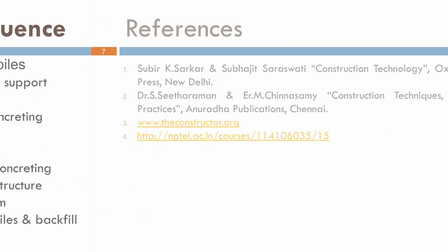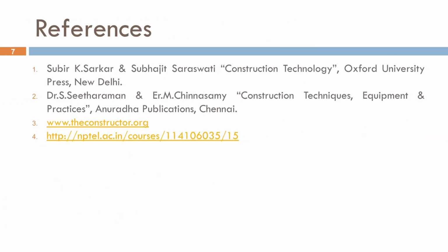To summarize, a cofferdam is a temporary but extremely important structure that allows engineers to construct foundations safely below the water level. Today we discussed its definition, planning considerations, different types used in water and on land, and the complete construction sequence. Whenever you see a bridge being constructed across a river, chances are that a cofferdam is playing a crucial role behind the scenes by providing a safe and dry working environment.